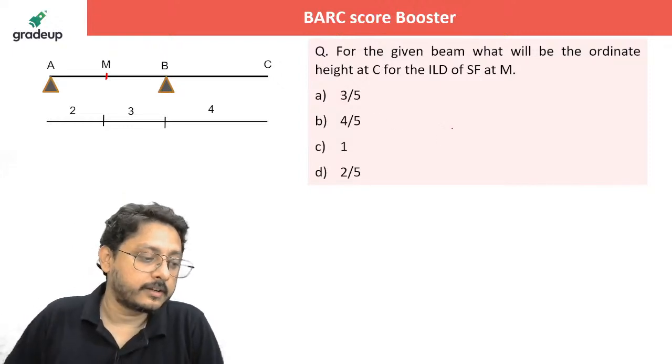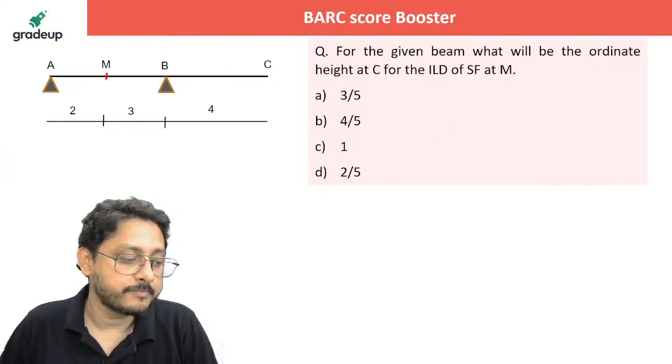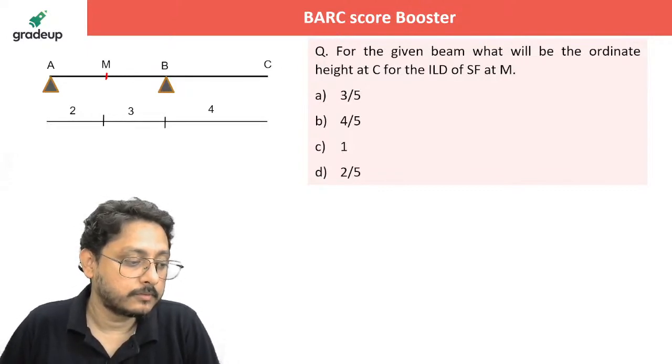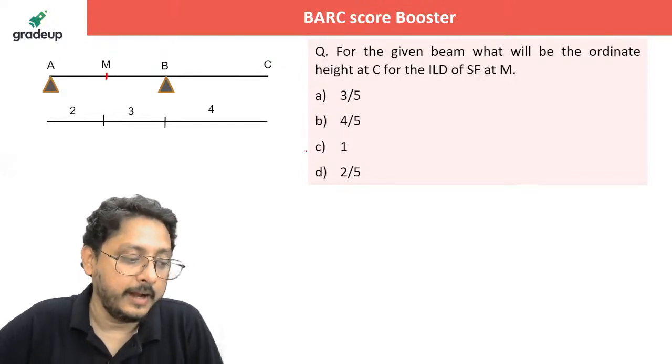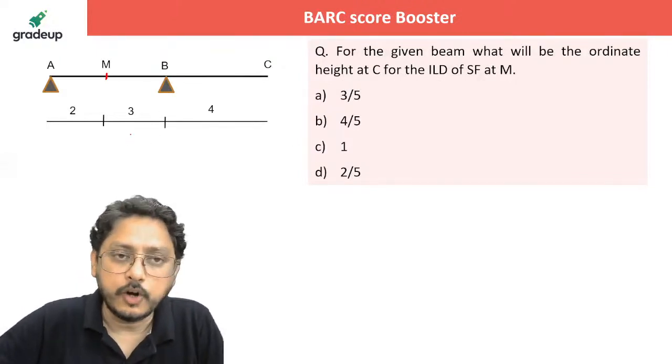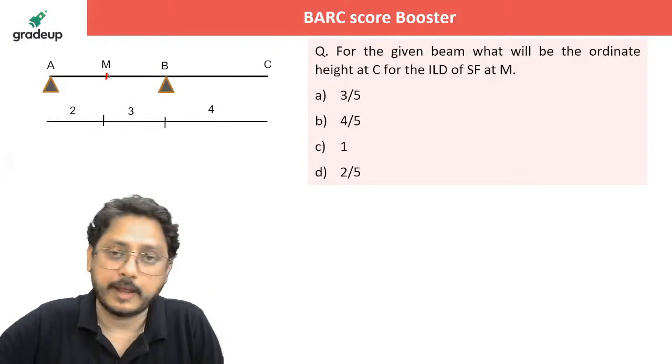Yes, it is curvilinear. But for a determinate structure, the ILD will always be linear. So first of all, draw the shear force ILD at M.